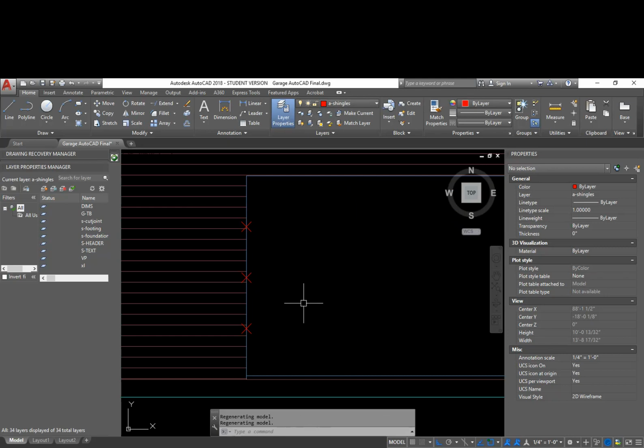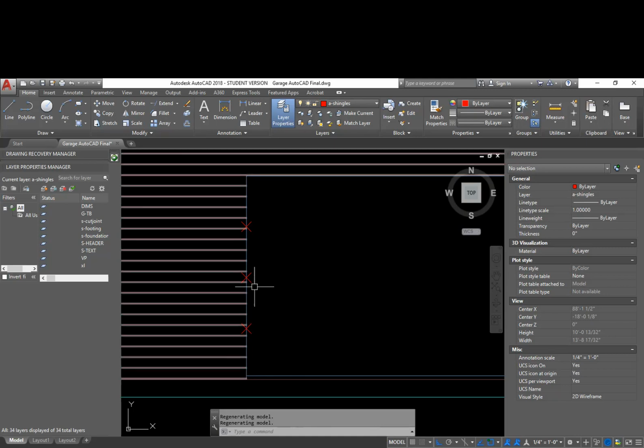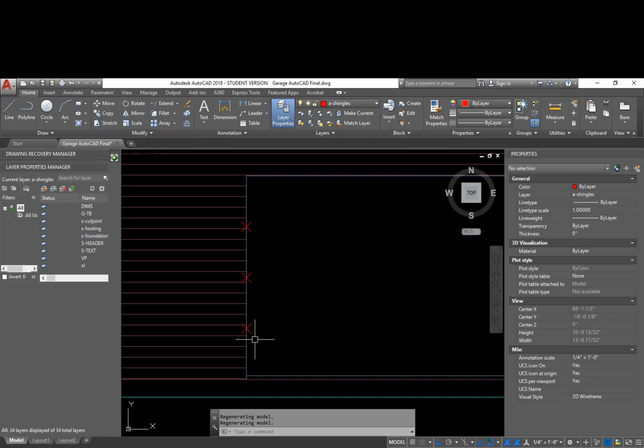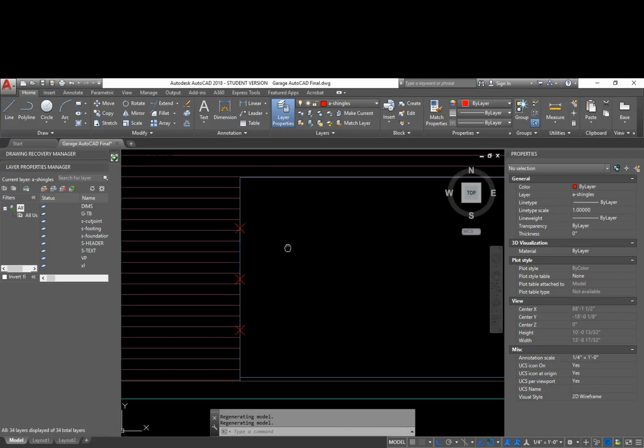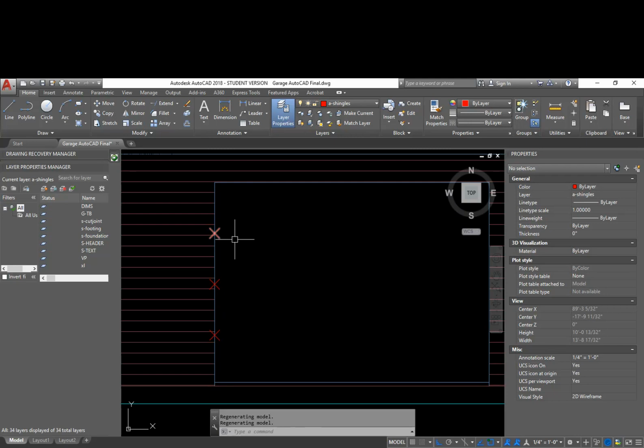And the problem with this is I chose to break this into 4 different sections, and if I have 1, 2, 3, 4, okay, so it did. So I only have 3 points, but it has 4 sections. So at this point, I can draw a line from this point. Now the point is not showing up in my O-snaps. So there's a couple different ways that I can do that.